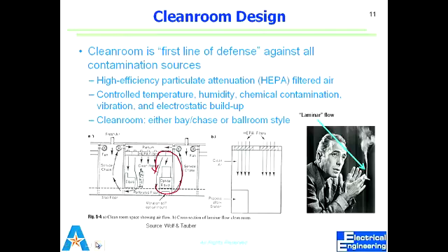It will become unstable. Stability will be lost. So you have this moment of inertia, right? If you have an unbalanced axis, what's going to happen? There are going to be unbalanced forces on the wafer, and whatever vacuum you apply, your wafer is going to fly away. And here goes your 1 year of hard work on the devices you have been making, right? So we want to control vibration.